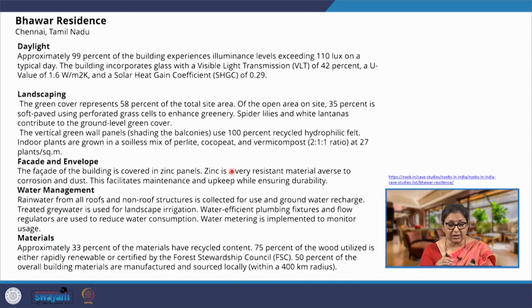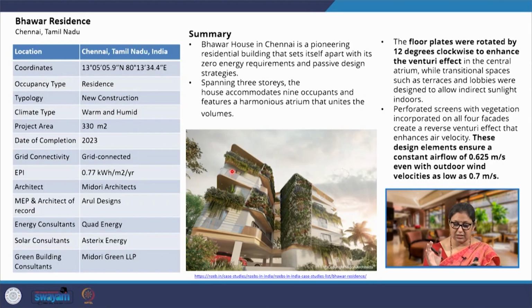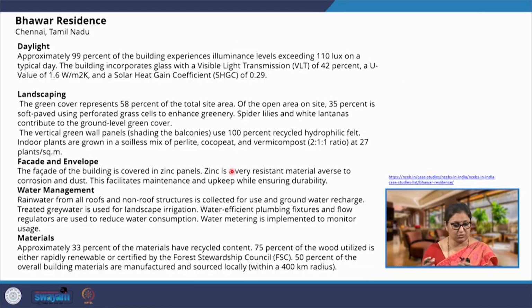So, what they have done is, the first thing is the design, as I always say. They have rotated the plates beautifully to enhance the Venturi effect in the atrium. So, there is an atrium, not a courtyard like the previous example that we saw, but an atrium which facilitates light and also ventilation, both of these things. An open courtyard also facilitates light and ventilation. Here the atrium is facilitating the light and ventilation.